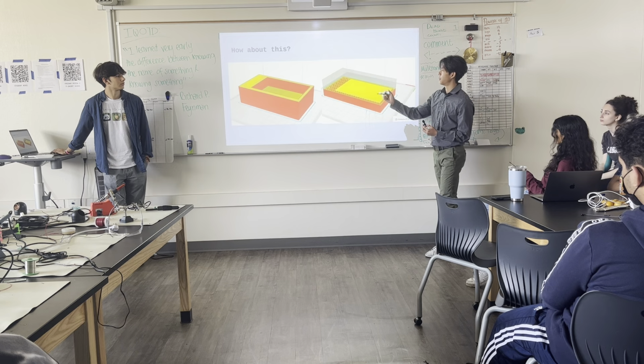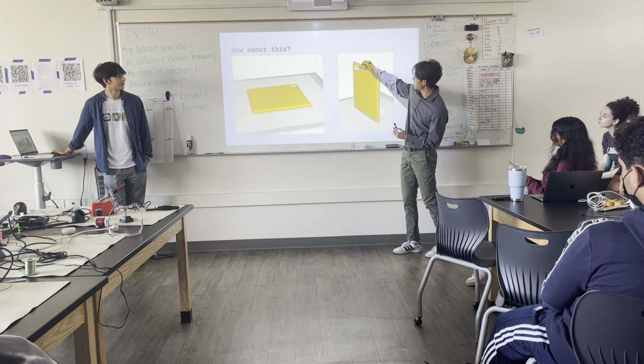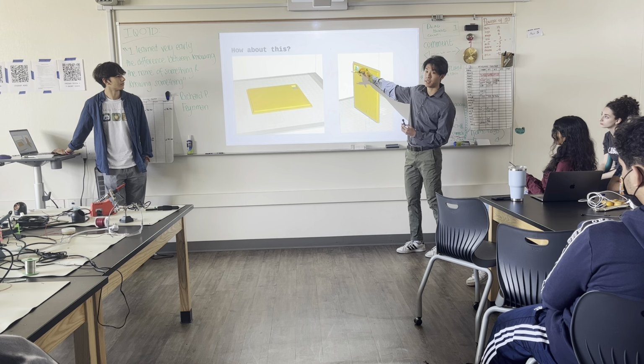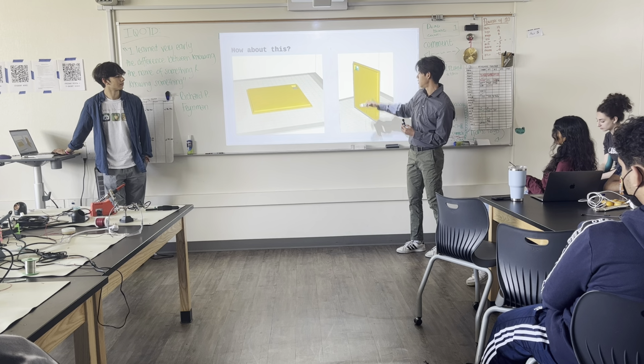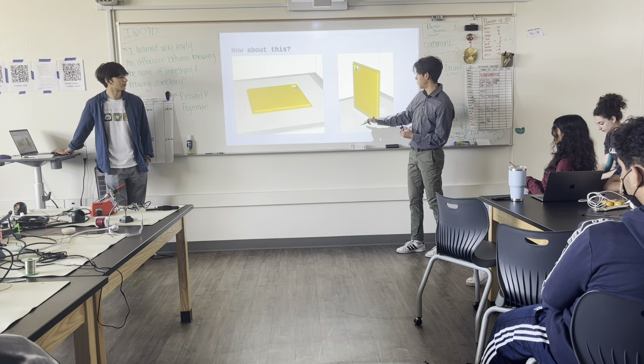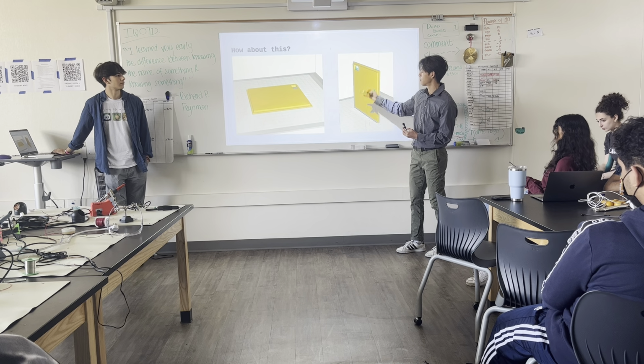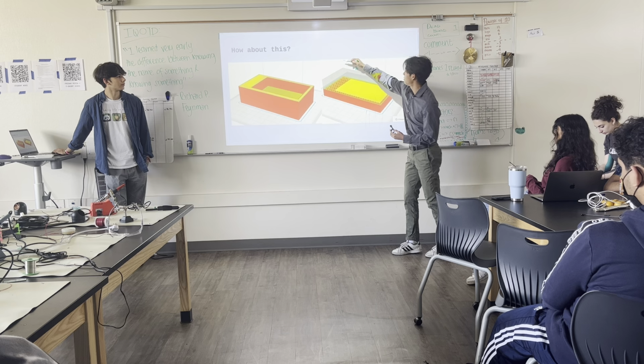And oh wait, go back. Sorry, one more thing. Also, there will be supports up here. And these type of supports are the worst ones, which connect from the piece back to the piece itself. They're hard to remove, rather than the supports that connect from the build plate to the piece. So yeah, it's worse.